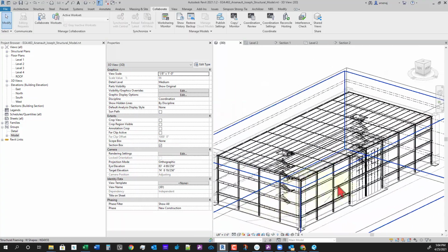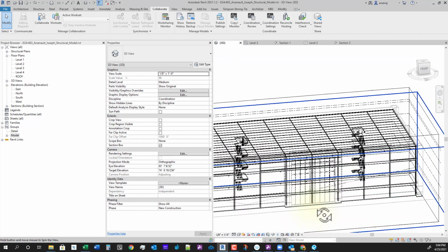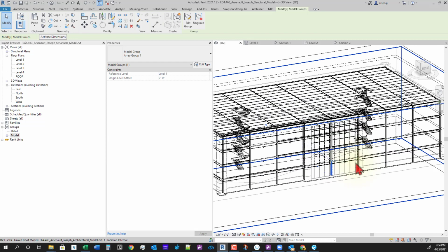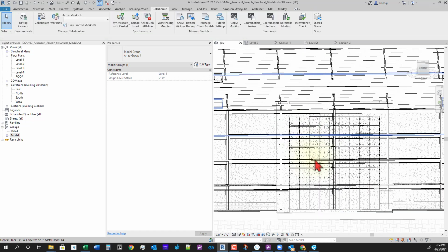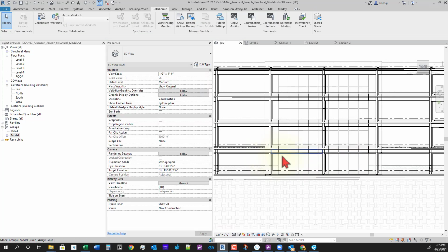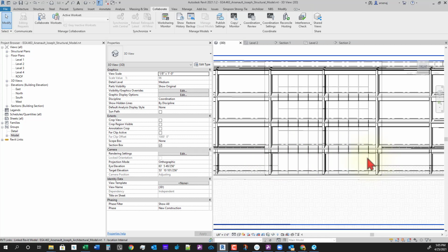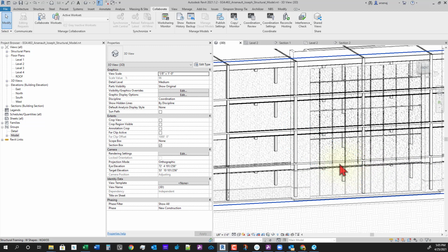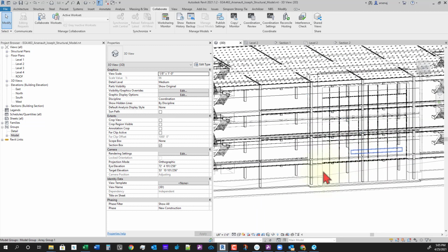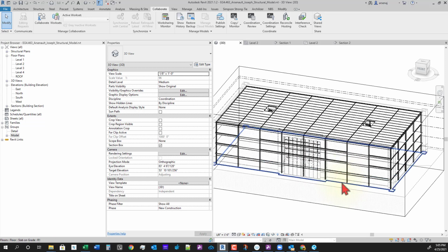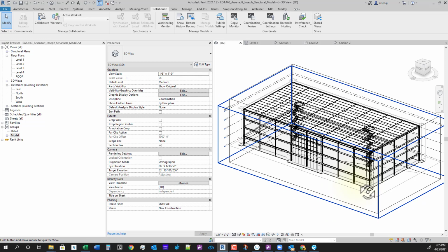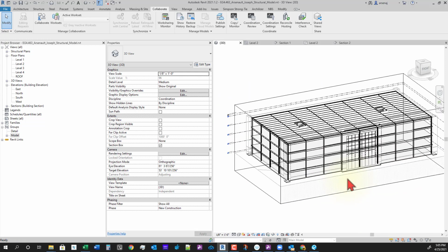All right, now we've got the start of our preliminary structure. Obviously here we won't want these beams to be in front of this window. We'll have to change some of our curtain wall, because we'll want the curtain wall to have opaque glass or spandrel glass at the beam lines, so that it'll be darkened glass and you can't see the structure behind it. So after we've done this, got our preliminary structure, let's go ahead and hit save.